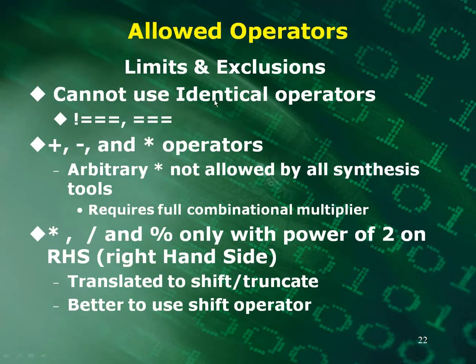You can't use the identical operators, if you remember those. And arbitrary multiplication is not allowed by all synthesis tools because it requires a full combinational multiplier. So you're going to have some limits if you're trying to do multiply and divide also.